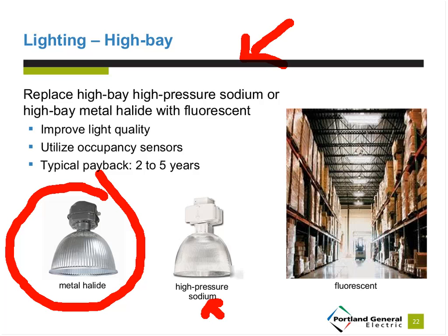So what we recommend, and what we see a lot of customers switch to, and get Energy Trust incentives for, is changing these out to high performance, high output T8 linear fluorescent bulbs, or T5s. Or we are starting to see some customers switch to LED fixtures, specifically if there are long hours of operation. It's the whole fixture that gets replaced.